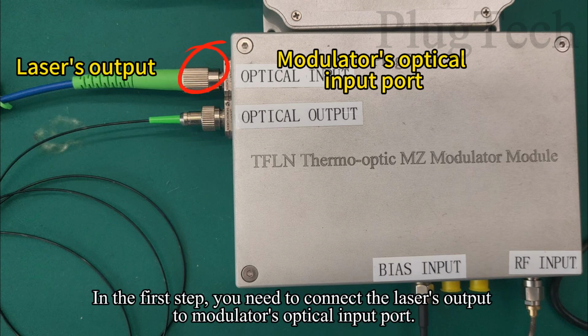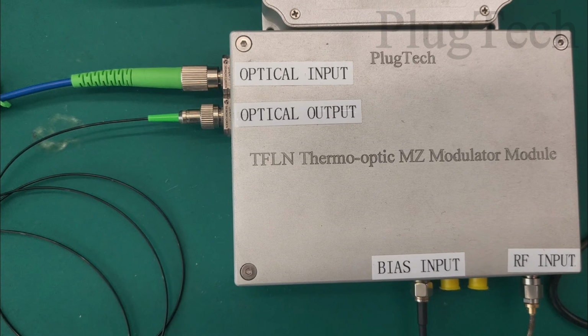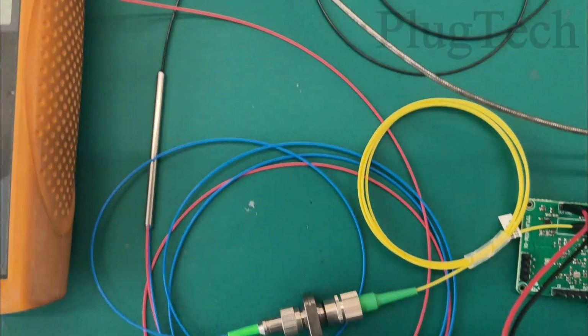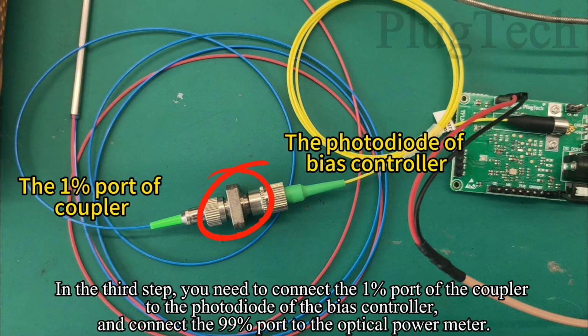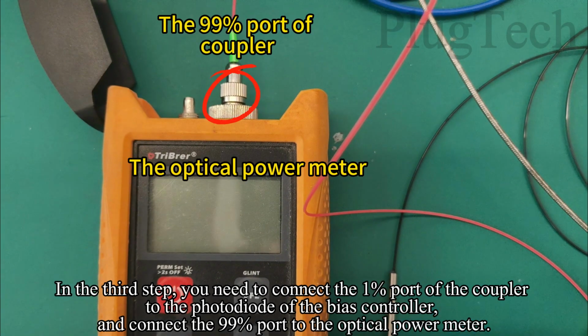In the first step, you need to connect the laser's output to the modulator's optical input port. In the second step, you need to connect the modulator's optical output port to the input port of the coupler. In the third step, you need to connect the 1% port of the coupler to the photodiode of the bias controller and connect the 99% port to the optical power meter.